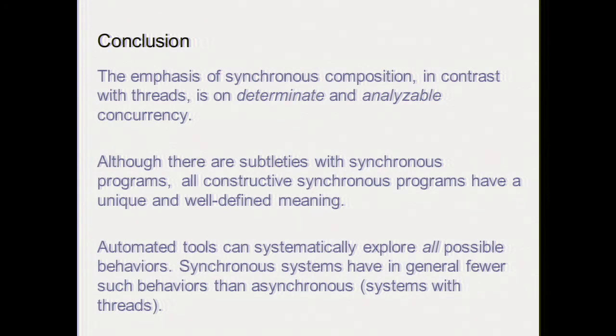So synchronous systems in general have fewer horrible behaviors than asynchronous ones. The horrible behaviors we've seen before are always due to a feedback composition, and the feedback in general is well-defined if it involves machines with that property. So a Moore machine is always well-defined, no matter what. But if you have Mealy machines in the structure, then you don't know, you have to do all the analysis that we said before. Okay?